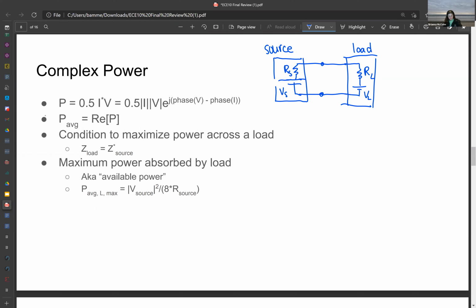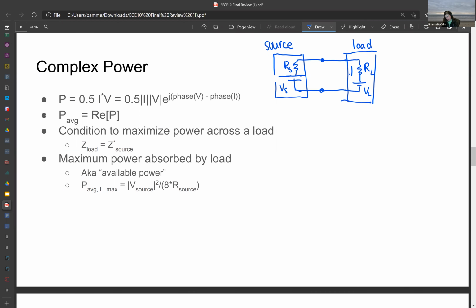So essentially complex power is the power connecting these 2 black boxes. So it's going to be the power that goes across here. And so you should be able to apply the P equals IV formula and figure out the power across that resistor. However, it's going to be more complicated as you're dealing with AC inputs. I've drawn it here for a DC input. That's not too difficult to deal with because it's constant voltage. But as you go to a tone like a cosine or a sine, it's not going to work as well, and you're going to have to deal with phases. And that's when we get complex power. And so complex power is given by this equation here.